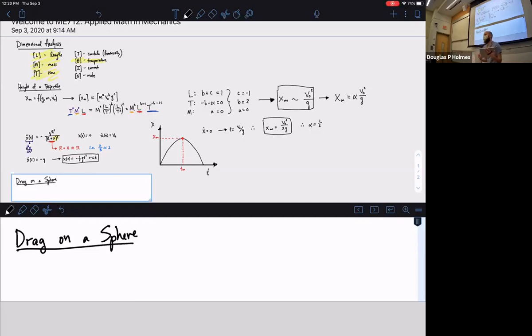So here's an example where you might be able to do what we did before and write down how the drag force should depend on various things by your own intuition. Or you could also look at the governing equations of fluids, the Navier-Stokes equations, and identify that there's a viscous term, there's a length scale that corresponds to the size of the object. We expect the density to be in there. We know that there's going to be some velocity of the fluid that's going to matter, or the velocity of the particle relative to the velocity of the fluid. And either way is fine. You can arrive at how you think the drag force should depend on these.